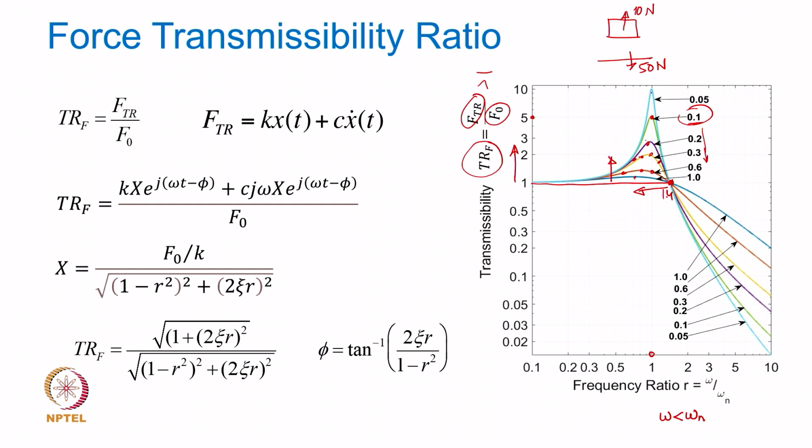Typically even rubber isolators will not have a damping ratio larger than 0.2 or 0.1 in that range. Even for a larger damping ratio, the transmitted force is going to be 5 times the excitation force. Obviously, if you increase the damping level, maybe 3 times the damping with reference to this case, 10 Newton of excitation will still transmit 20 Newton of force in the ground.